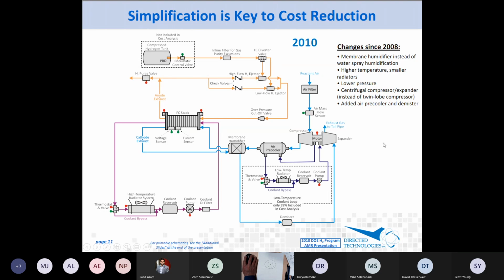Hey, Jeff? Do you think they recirculate the hydrogen here that comes out of the fuel cell? I think it helps with hydrogen utilization. And if I'm not mistaken, I think this hydrogen is also carrying some relative humidity to basically humidify the anode side. Well, that might be right. It might have picked up some humidity. But remember, because of osmotic drag, the water on the anode side tends to get dragged through to the cathode side. So anyway, it might be the case that it gets somewhat humidified by this loop that's happening here.